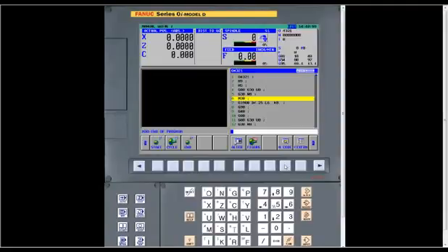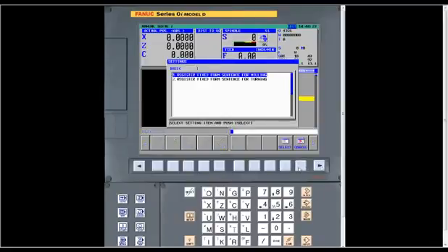Now, I showed you my fixed forms, and after this is over, if you need to, contact me direct. I can help you develop these fixed forms. But then to actually make them yourself, if you go right shift until you see a soft key called settings, you go into that. It takes you into the basics where you can either set them up for milling or turning.